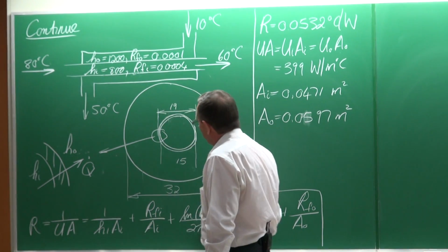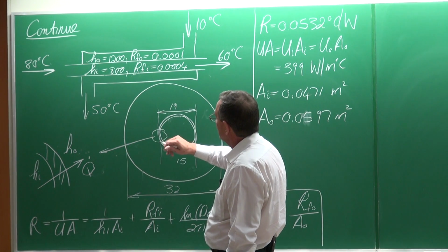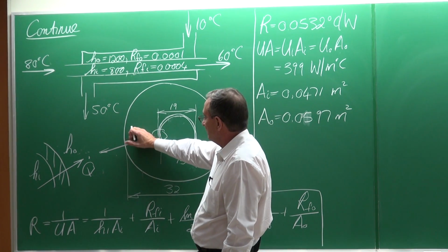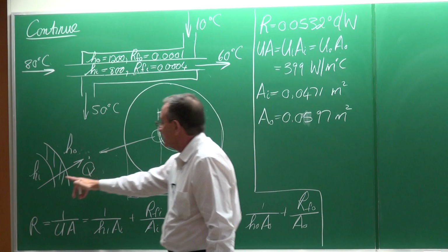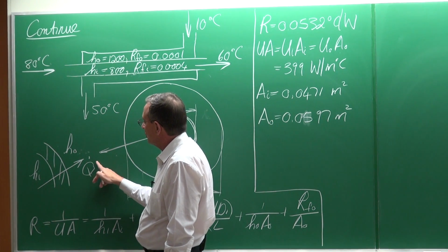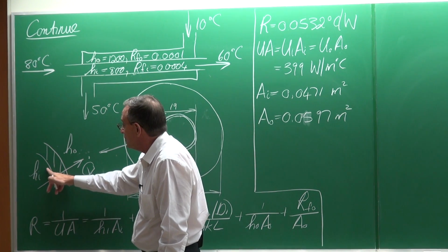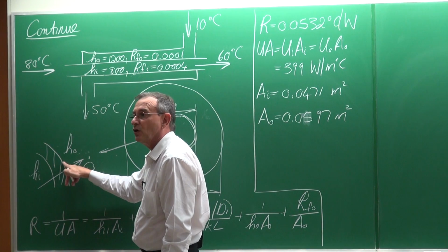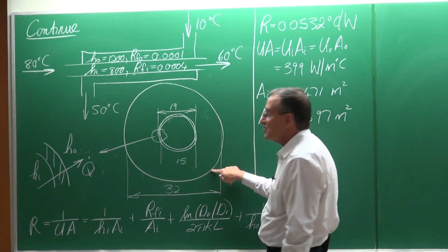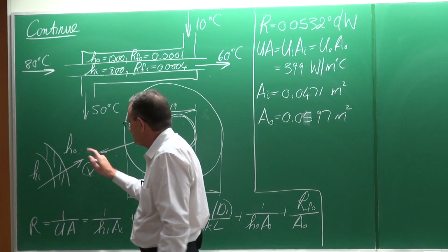It is all about the fact that at any specific wall, if we've got a heat exchanger, if this is one fluid and that is another fluid, there's heat transfer occurring. There's the heat transfer rate, in this case from the hotter fluid, of course, to the colder one. What is important is the heat transfer coefficient on this inner wall and the heat transfer coefficient of that wall. What the heat transfer coefficient is there is not going to matter. It's only where the heat transfer occurs.